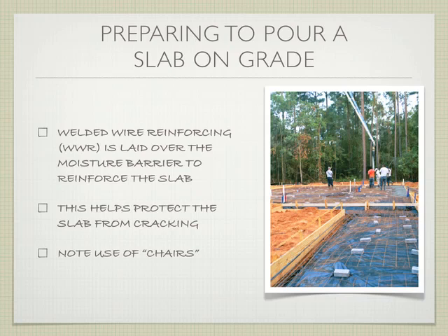It doesn't prevent it from cracking. So if you had a major earthquake and it caused the floor of the building to separate or crack, that would open back up. Now it is somewhat elastic, so if it was a very small crack, it would probably stretch over the small crack. But if it was a big crack like the one up here or the one in there, that kind of crack wouldn't seal up. Now I could pull up the floor, reseal it, and it would be okay again. But that's something that you're subject to.